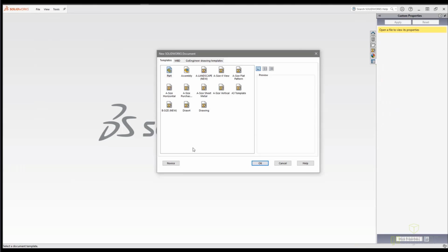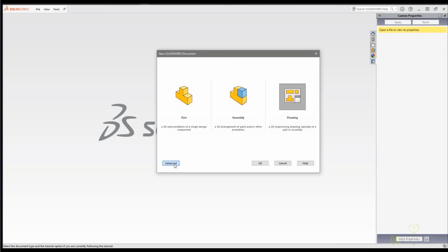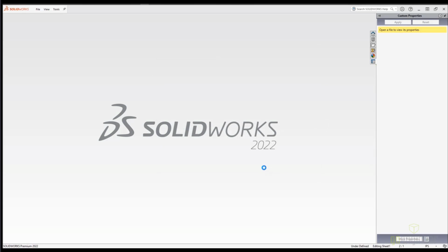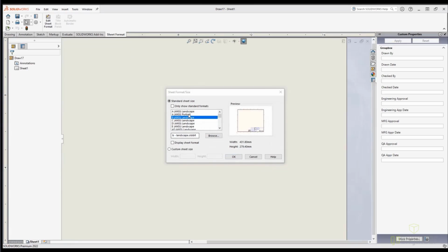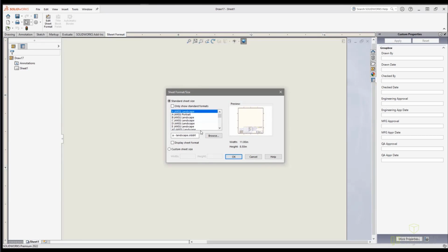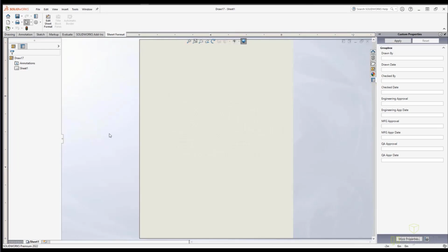So that's working with some of the templates that you might already have. If I look under the SOLIDWORKS side of these, these are templates that are already included with your installations. We can actually go through and create a new drawing template, and it's very simple to work with because it's all sketch entities and the tools built into the tab in the files here that we can work with. So click OK. In this example, what if you wanted to work from scratch? You're working with a completely new blank sheet. You want to create a new drawing template entirely here.